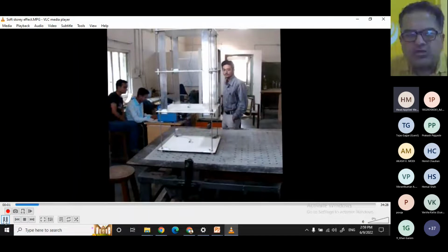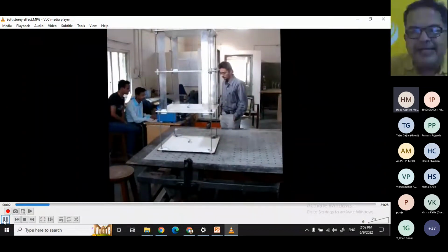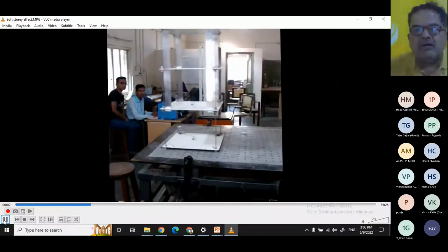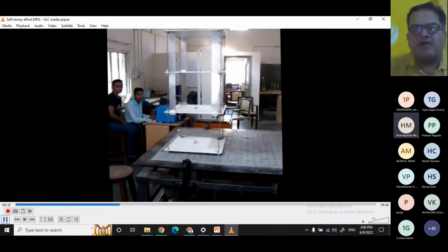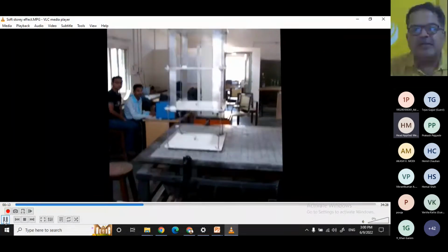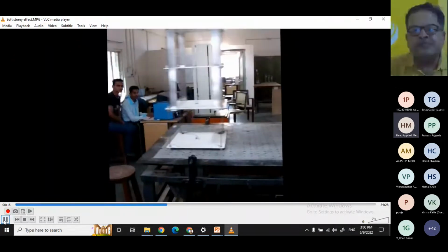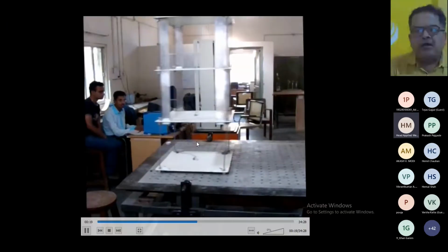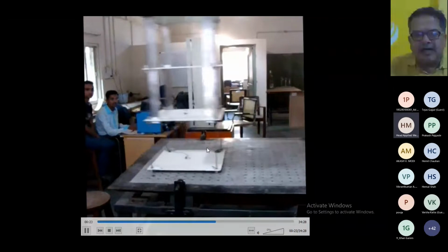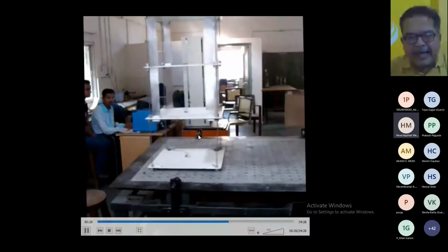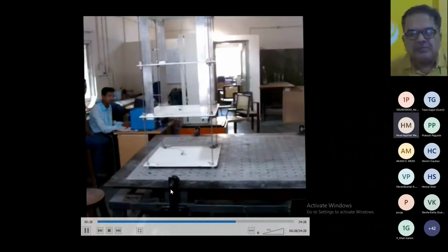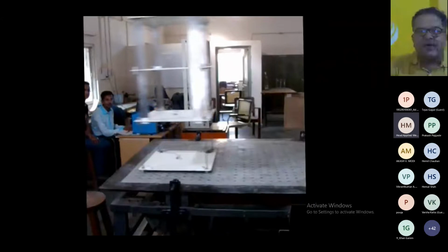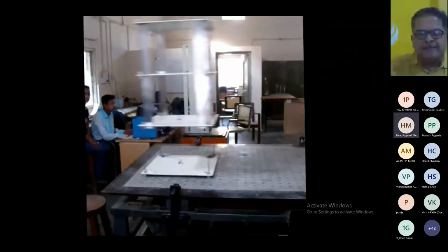Remember, this is very important. These are our ME students who are performing this test, and I think they try to understand soft story effect. Okay? Just look at the behavior, right? If you see this, you will find that the upper part is behaving like a rigid body, and the lower part is basically having most of the deformation, right? Most of the deformation is at the lower story, right? Upper part is deforming like a rigid body, right? You can understand this now, right?